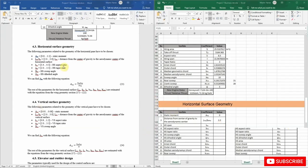We will choose the aspect ratio to be equal to 4, and the taper ratio will be equal to 3 in this case. Then we need to choose our sweep angle, and I'm going to choose a standard 35 degrees. Then the dihedral angle, I will choose it to be 0, because normally on horizontal stabilizers there is no dihedral angle, so it is usually straight to the horizontal plane. And that's it here. Then for the area I will choose 13, but this will probably change. I'm just guessing here, but I think it should be about 13 square meters.